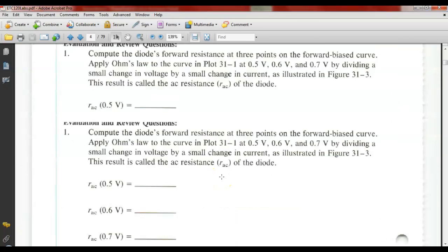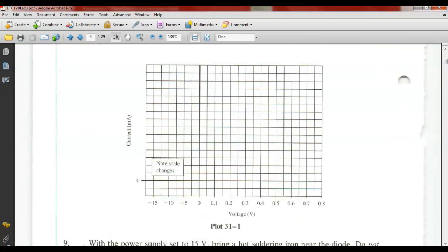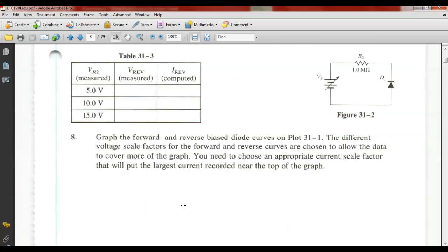So the circuit that we have, let's just bring up the lab. So the circuit you're going to be hooking up is where you're going to draw your VI characteristic curve. We'll come up with the current, and then the voltage is set up for you. We're going to have to rearrange this. This guy here has a breakover voltage of 75 volts. I don't know where they came up with this chart. So at 15 volts, this guy wouldn't be doing nothing. So we're trying to see where it breaks over. Okay. So this is a circuit that you'll be hooking up.